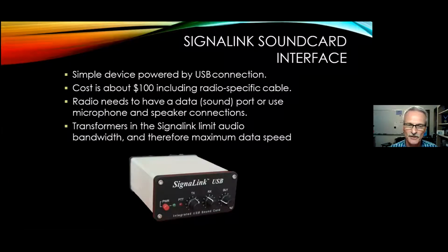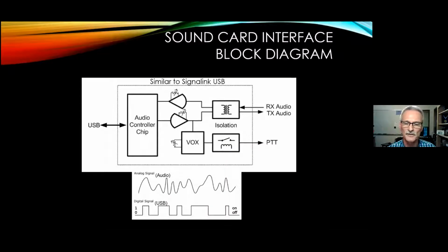You have to have a way to connect this to your radio. So either you have a data port on your radio, which unfortunately a lot of the manufacturers are discontinuing, that data port on the back. But if that's not an option, then we can connect to the speaker and microphone connections. And the SIGNALINK does have transformers in it that do the ground isolation, and that tends to limit the audio bandwidth, okay? And therefore the maximum data speed that we can push through a device like this. And I'll talk some more about that here in a minute.